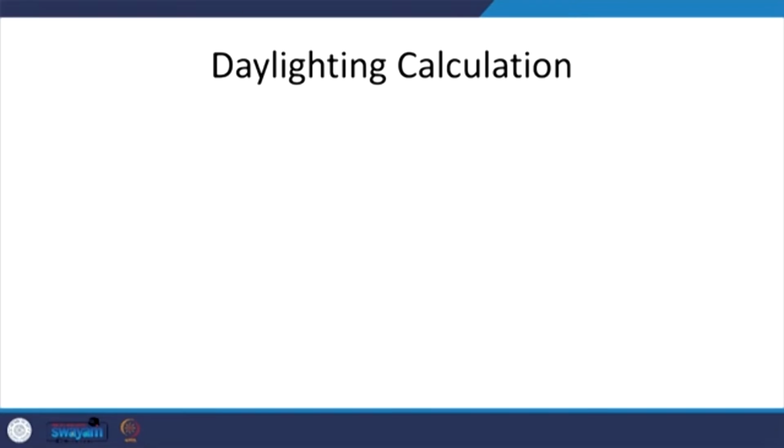For example, LEED requires at least 75% of the habitable area to be daylit, and daylit also has a range of values. In LEED, daylighting is defined using daylight factor; sometimes it is also defined using illuminance, or other terminology which we have seen as part of our lecture on daylight. The most commonly used one is the daylight factor.